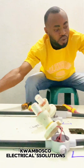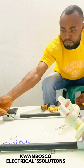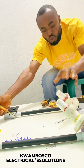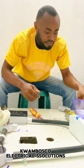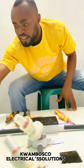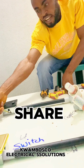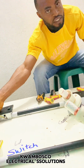You move to the next one, you off, the thing is still bringing the same issue. This one is off, this one is off, there's no light on this circuit. So now these two are okay, the fault is not from here. Now you come again to this one that is still on, you off this one and check. This one is on now, the light is back. When I off it, you realize that the light is off. That means the fault is from this circuit, this socket.